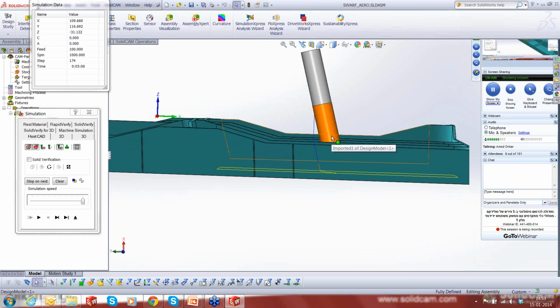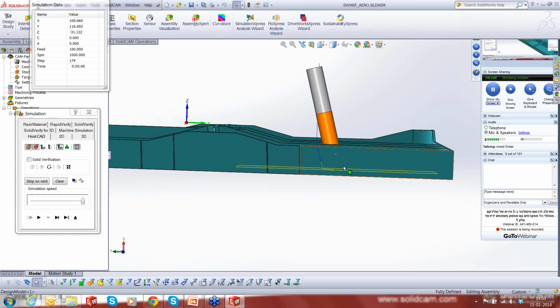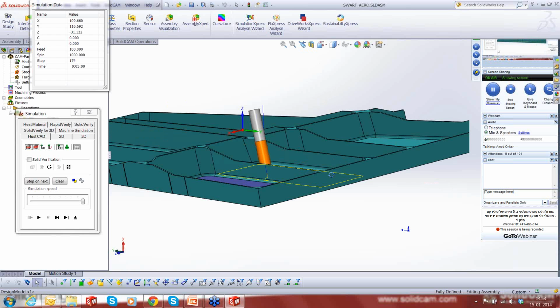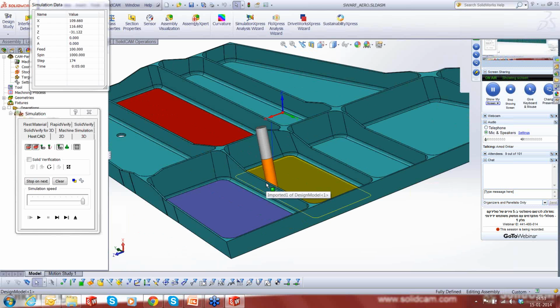It did not change the angle because that would have again resulted in some surface variations in terms of finish. So it has kept the angle as close to the influencing surface as possible so as to avoid any variations in the surface finish on the surfaces that it is cutting. Very smart.